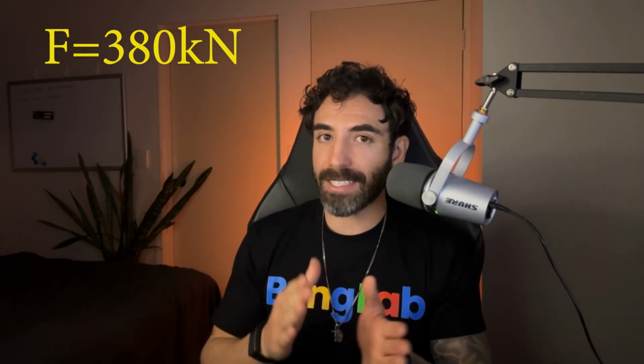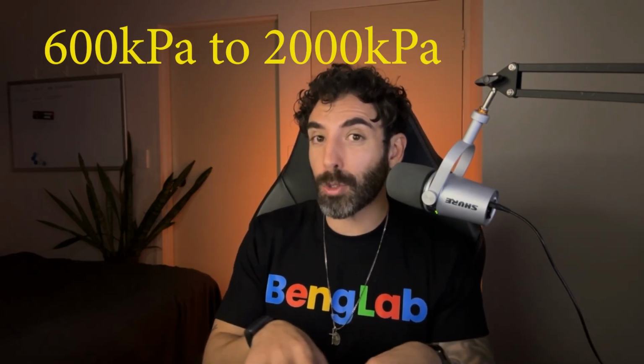If you need more capacity out of that pile, if you need more than 380 kilonewtons, you will have to utilize the pile skin friction, which means you will have to socket the pile into rock. And drilling rock is very expensive and very laborious. So what Andrew did was contact the client and ask them to engage another geotechnical engineer. Now the second geotech report cost the client an extra $7,000. However, the geotechnical report came back with a bearing capacity of 2000 kPa. So it went from 600 kPa to 2000 kPa.